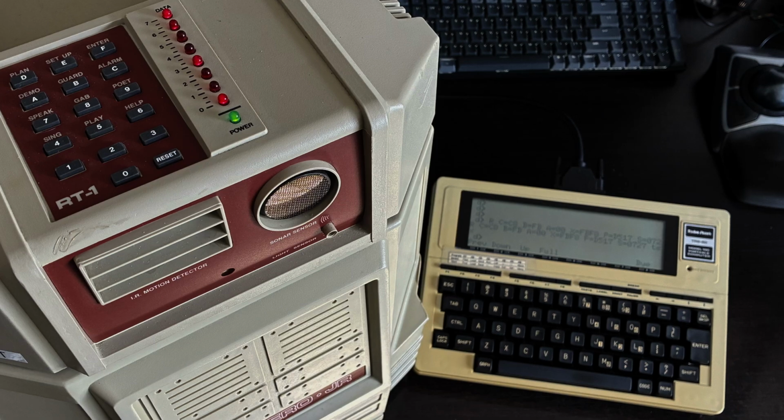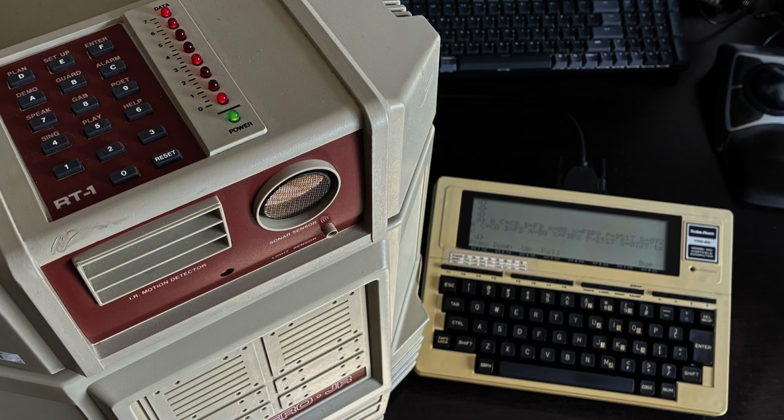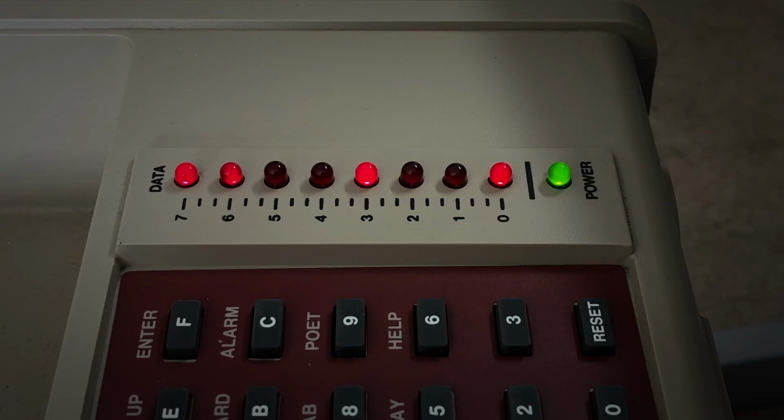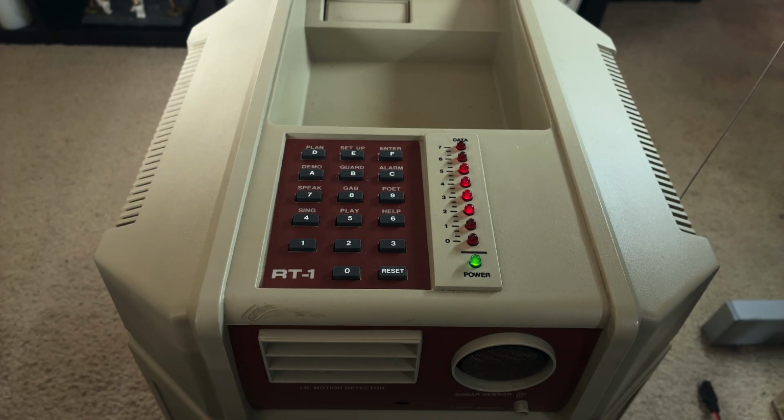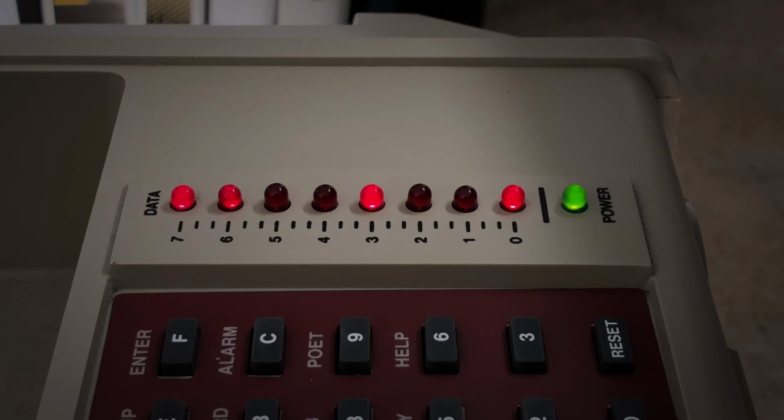As to that final bit pattern we see after every speech output, it seems to be a byproduct of the ROM routine that shuts down the speech chip after it finishes speaking. It's always a C9 bit pattern, 11001001. Could it be related to this particular sound? Time may tell. For now, there we have it. We've mastered the fine art of the Hero Jr.'s other form of user output, its LED lights.